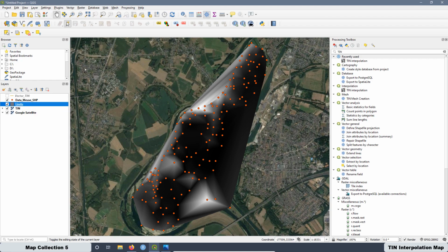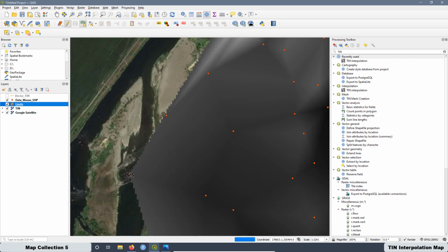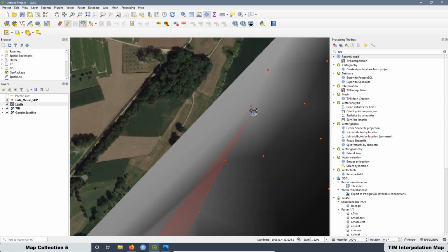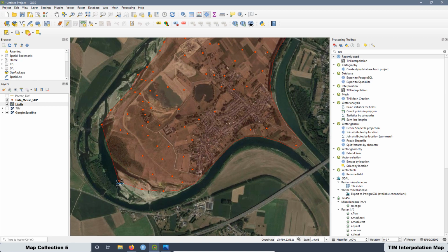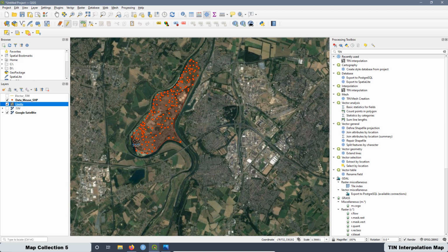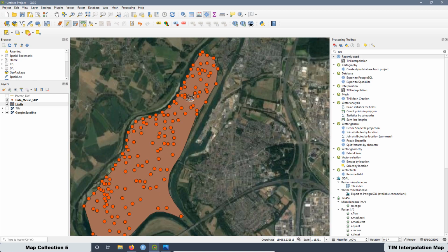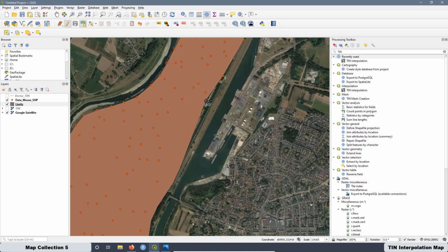Then press OK, and now we are going to edit. Then select the layer, press the pencil, and we are going to use the samples to create the limit. Then select this option, zoom in, and let's go to create it. Just selecting the points, we can join these points to create the mask, okay? Then I'm going to pass the video faster. Well, that's it. Then right click to finish, select a name. For the ID, I'm going to put number 1, and okay.